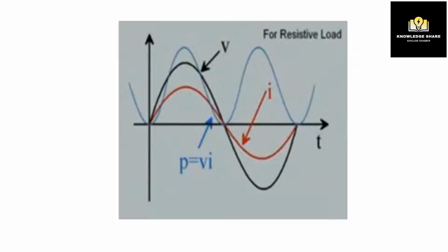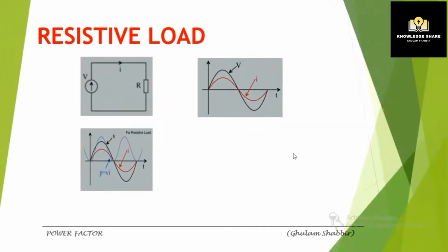Power starts from zero and gradually rises up. When the voltage and current are zero, power is also zero. But when both voltage and current are negative, the product of that is still positive. Therefore, the power waveform continues to rise up and becomes positive. The power waveform has no negative component. It has a frequency double that of the current and the voltage waveform, as shown.